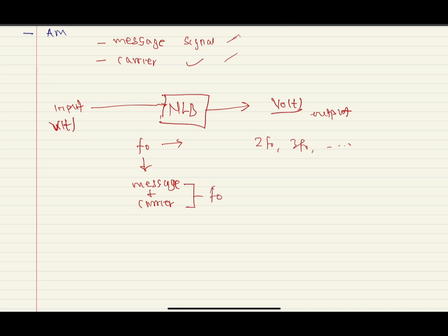When it comes out after modulation, there are integral multiples of this fundamental frequency, which is the original signal that we placed into the input of the nonlinear device. Due to the harmonics that the nonlinear device created, we have gotten unwanted frequencies, or unwanted noise, added to the original signal that we want to modulate, and therefore we need to filter it out.